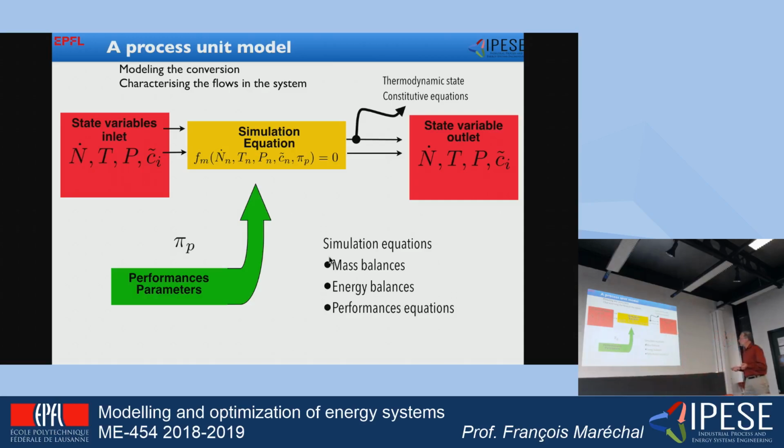Now, another problem is going to come when I have to write the energy balance. Because here I do have temperature, pressure, and composition. But I do not see the energy there. So what would you do then? So I have composition, temperature, and pressure. So what will be your solution in order to be able to write the energy balance?